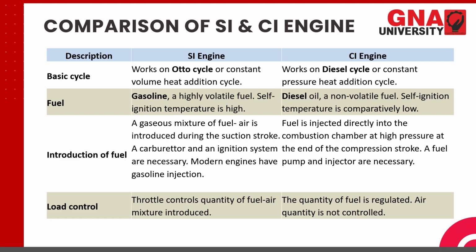Why is it called quality control? Because as we press more accelerator, more fuel goes into the same amount of air. As we press less accelerator, less fuel goes inside. So the quality of the mixture is being varied.